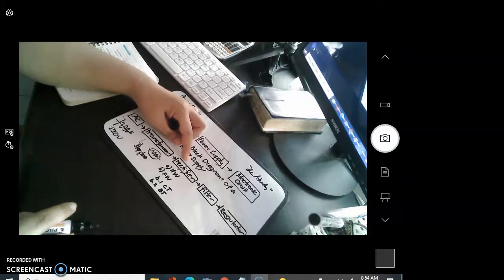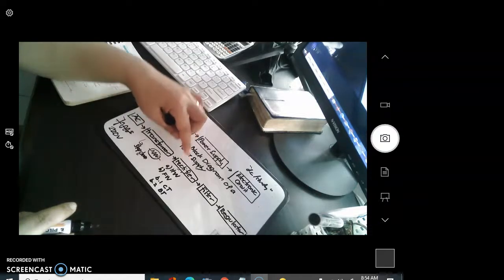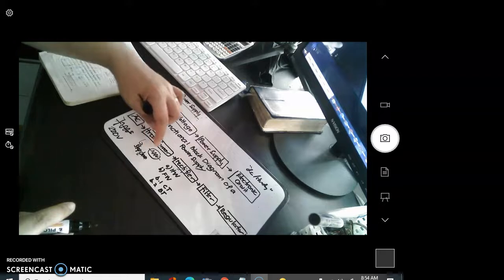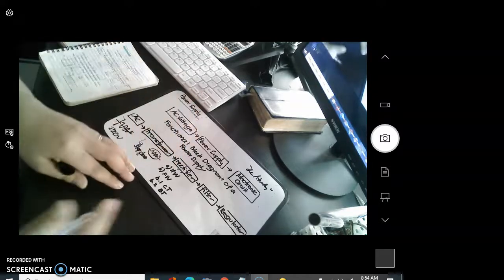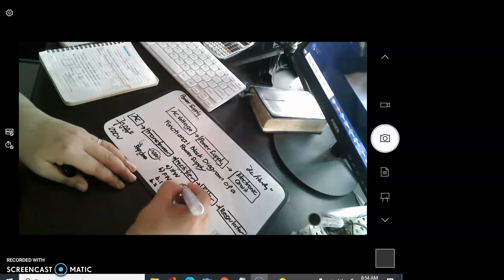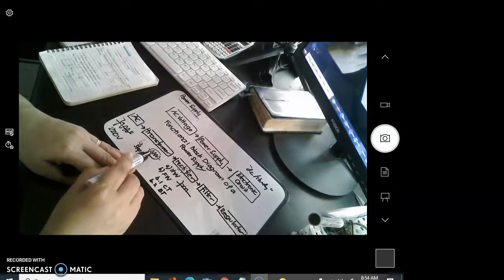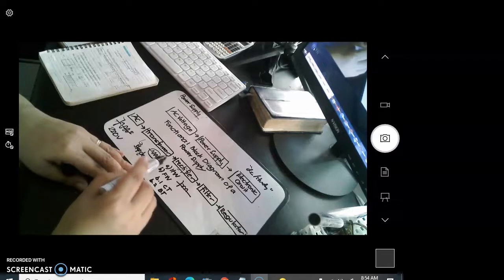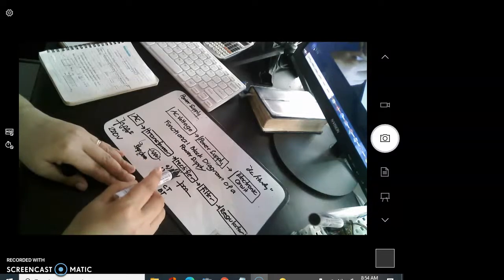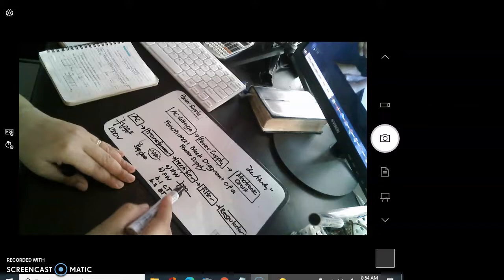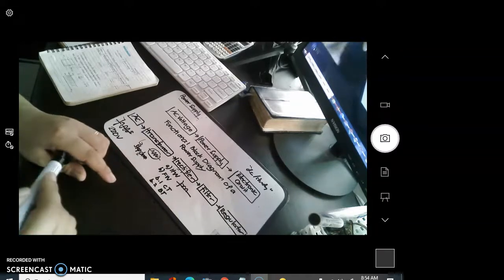That's the reason why we have what is known as the diode rectifier. It will rectify the input signal and will produce this output. So instead of having alternating positive and negative values, once this signal passes through the rectifier, it will simply remove all the negative values, leaving only the positive.